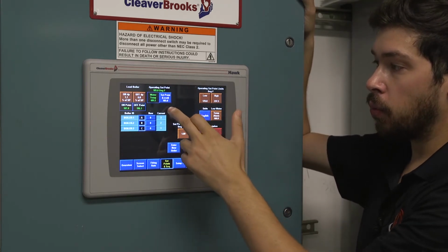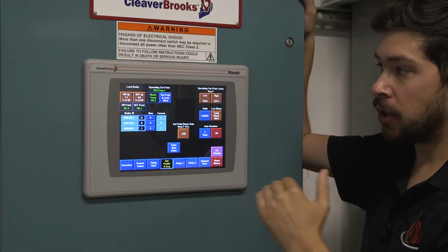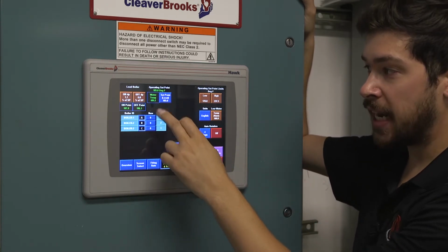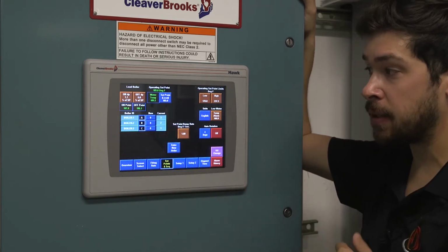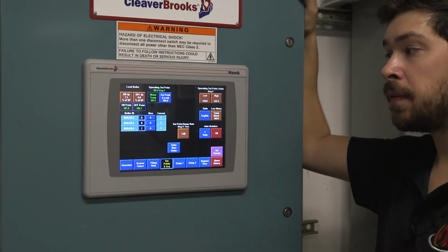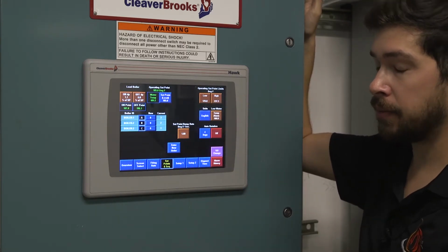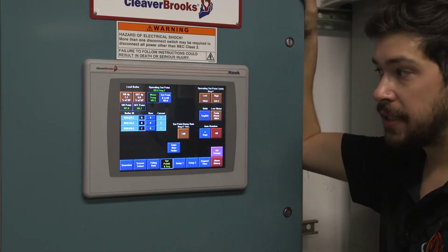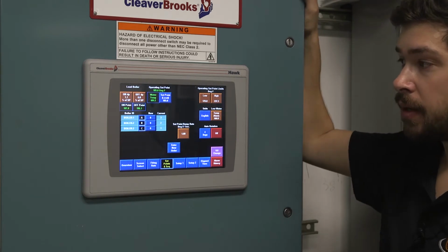So we don't have enough load to keep at 185 perfectly, so we start creeping up: 189, 190, 195. Once it hits 196.1, all right, that's enough. You're too hot. It shuts everything off and lets the system naturally cool down, adding whatever load, taking that heat out until we get to 187.